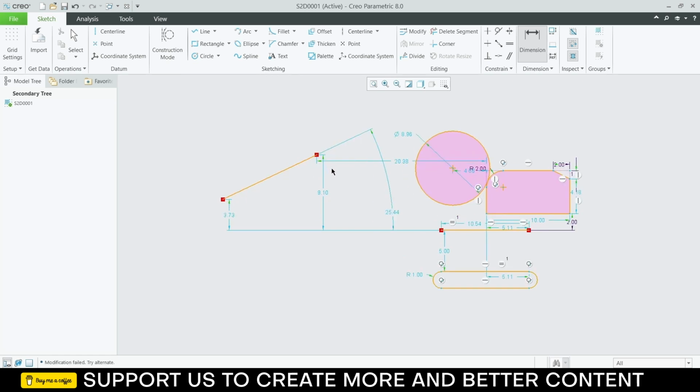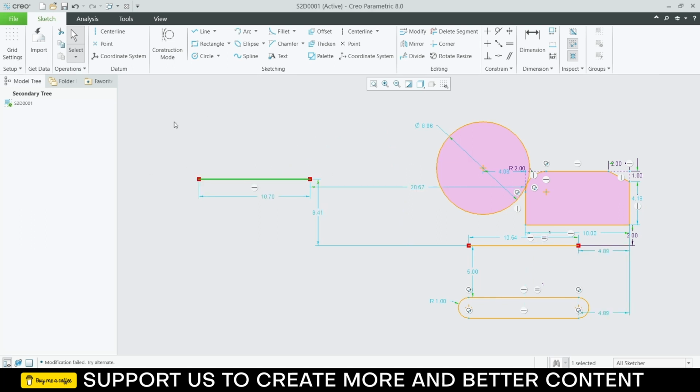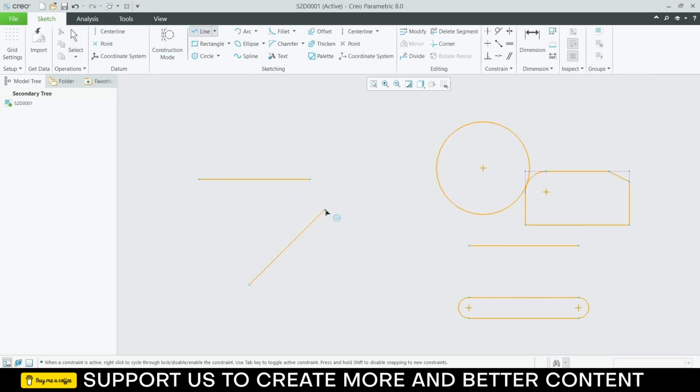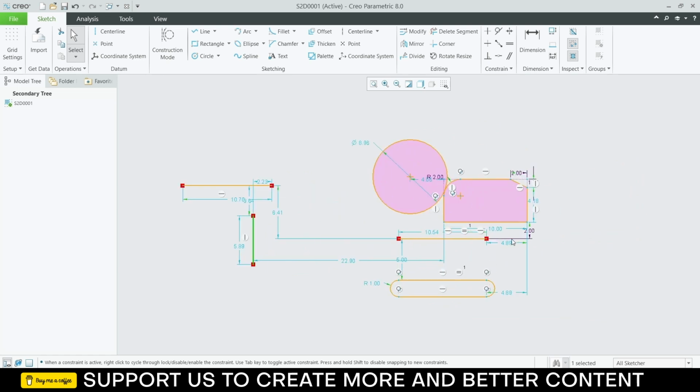Okay, there are other issues as well. For example, notice this dimension. This is also an issue. So there are many issues here. Let's see one by one how to resolve them. Select this line, just click on horizontal. Or let's say I draw a line like this, select the middle mouse button again. Now select this line, click on this vertical icon. As you can see, I made it a vertical line. In that way you can create a lot of things.